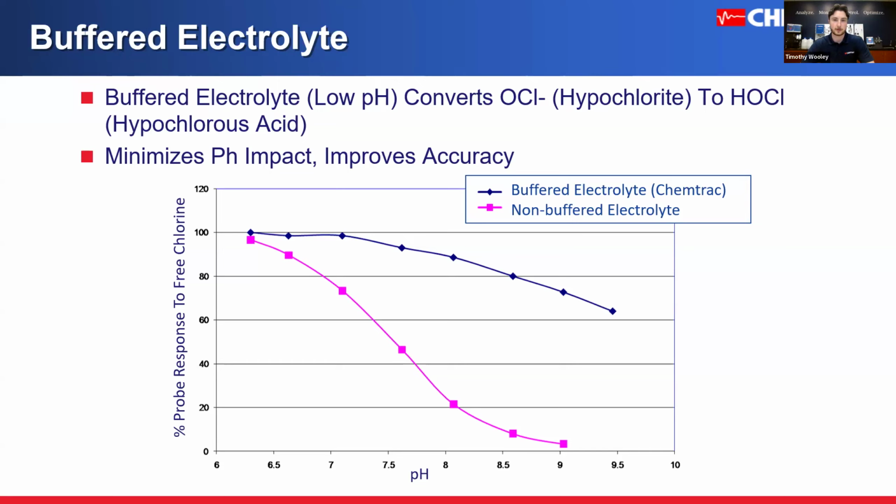But with the use of a buffered electrolyte, which is included with all these chlorine probes, it greatly resists those pH changes. That neutralizes those acids by having a weak acid-base pair, and that keeps the environment stable even as those reactions occur. This stability is very necessary to ensure that the probe signal is reflecting a change in chlorine and not a fluctuation in pH.